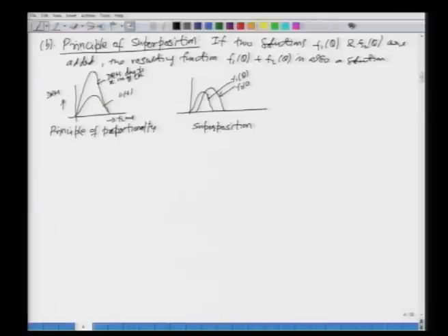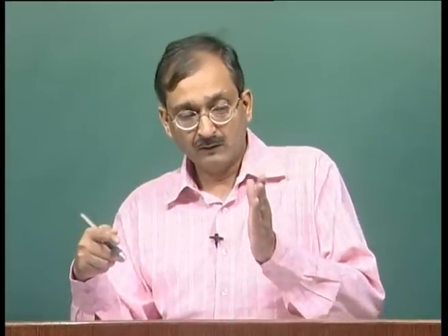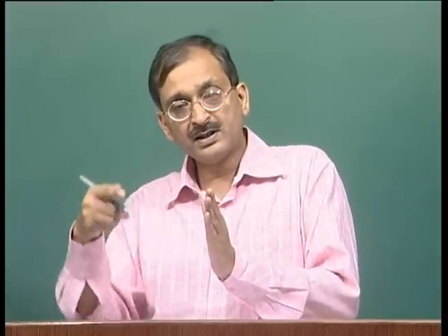F2. All right. So, what we are looking at is we have two different direct runoff hydrograph responses from the catchment due to two different input impulses. These may be, let us say, 2 unit hydrographs. 1 centimeter of rainfall occurs at some time, it produces a DRH. 1 centimeter of rainfall occurs after some time, that also produces the same response. Okay. Now, how do I find the combined response?